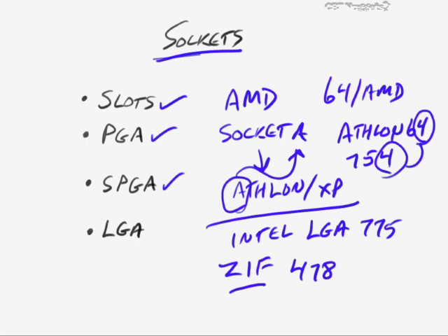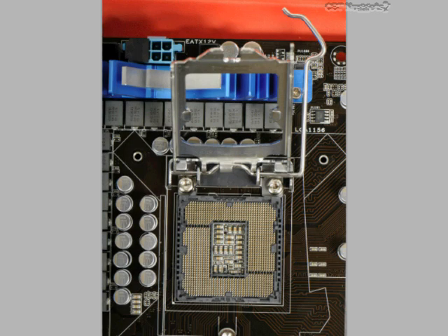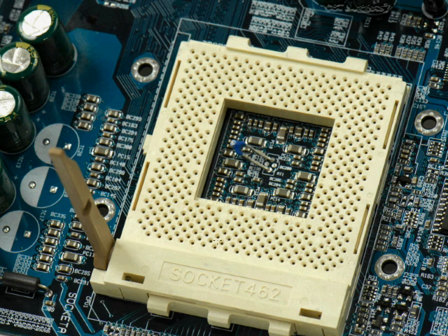And then if you actually look at the sockets for these, let me try to find an example here. That's the wrong one. Let me go to this one here. There we go. This is a socket that uses the kind of processors for a staggered pin grid array. You can see here that they're not lined up perfectly straight across. Notice that these are indeed staggered as they go across. And you would drop the processor in here. Now, notice that there's also a keying on this. In this corner, there's a pin all the way to the corner. In this corner, there's a pin all the way to the corner. This one, there's not. It goes straight across here, across these last 3 pins. This one the same. There's not a pin in the corner. It goes straight across right there.